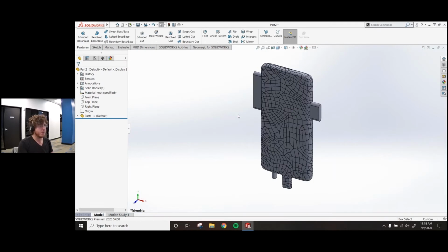Different units. What that warning was saying is that the units might be different, while my template is different between the two that I just created. Something that you have to remember is mesh data is unitless. While we're already talking about complex topics, with the triangles being like a surface, if you export out a mesh, it might be 5 by 12. But what is that 5 by 12? Is it 5 by 12 inches? Is it millimeters? Depending on what you bring it into, that's what really assigns the units to our mesh data. But in our case, we have our phone right inside of here.